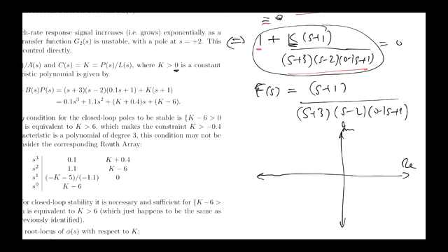We know that the poles and zeros of F are important. In particular, for small values of k, the root locus will consist, in this case, of 3 points close to the poles of F. For any value of k, we get 3 zeros of this rational function because we get a cubic on the top once we multiply 1 by the denominator here.